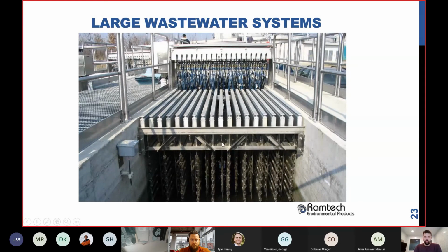So this middle module probably actually has 9 sleeves, and one of those sleeves would have the UV sensor in it, detecting how much energy is being outputted by this whole bank. It can be used to monitor how fouling is doing on the sleeve, because even if you have chemical mechanical cleaning, it's going to need to be cleaned manually every once in a while. And it can be used to modulate the output of the lamps. These ones specifically can go from 100% peak down to 60%, depending on what you need.